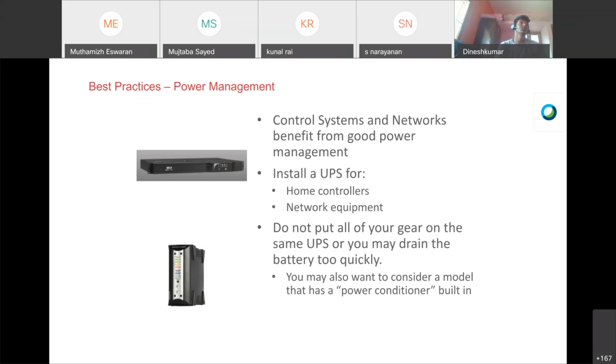At least have your basic primary devices like networking products, maybe power-sensitive equipment like controllers, or your cameras, peripheral monitoring, and a few lighting circuits. Put all those things on a UPS or maybe a power manager. And if you are using a DG, you always need a power conditioner. That is very much important. All right, so that is on the power side.